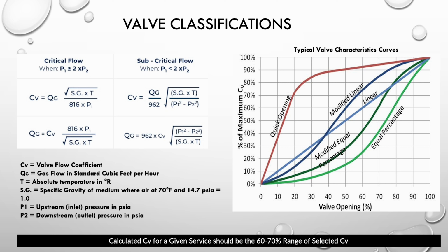So you don't get to say, hey, I want a ball valve or I want the gate valve that has a linear or equal percentage. That's not how it works. What it works is that you have a process control. You have a given process variable that you, for example, want to control. And that process variable, either you want it to be reacting slowly or reacting aggressively fast.